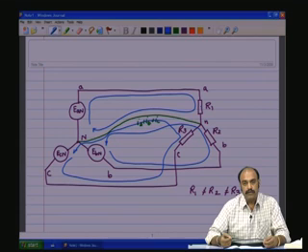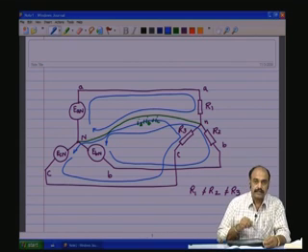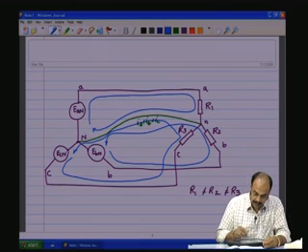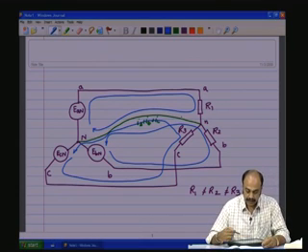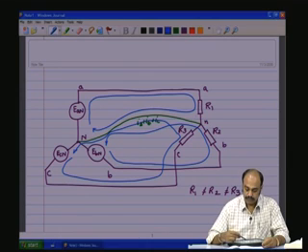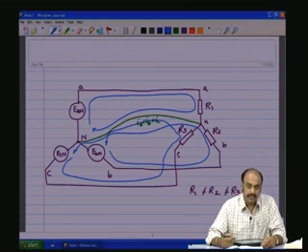The voltages across all the three phases will still be the same as decided by the source, whereas if this green line, the neutral, is not connected, then the unbalanced currents will get mixed up and flow through the other loads, and then you can have voltage distortions.